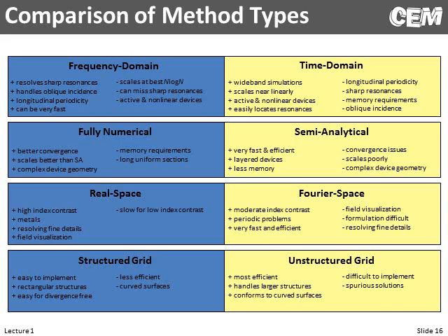Structured versus unstructured grids. For the most part, we're going to be doing all structured grids. This is the easiest thing. So you'll lay out an array of points. They're all equally spaced and distributed, so it's very easy to manipulate that. Unstructured grids, you probably have seen that with finite element methods, little triangles meshed everywhere. That's called an unstructured grid. It's a lot more efficient, but a lot more of a pain to formulate and implement.